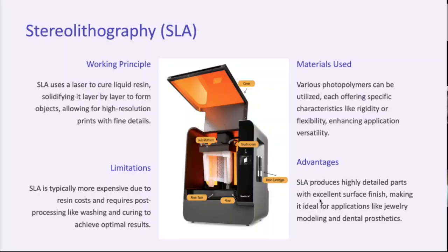So that was the thing with SLA, and we have big SLA printers where we can print a whole chair in one stretch. But it requires a high setup, and the resin cost is very high. So no one will try to use SLA for making such big parts.